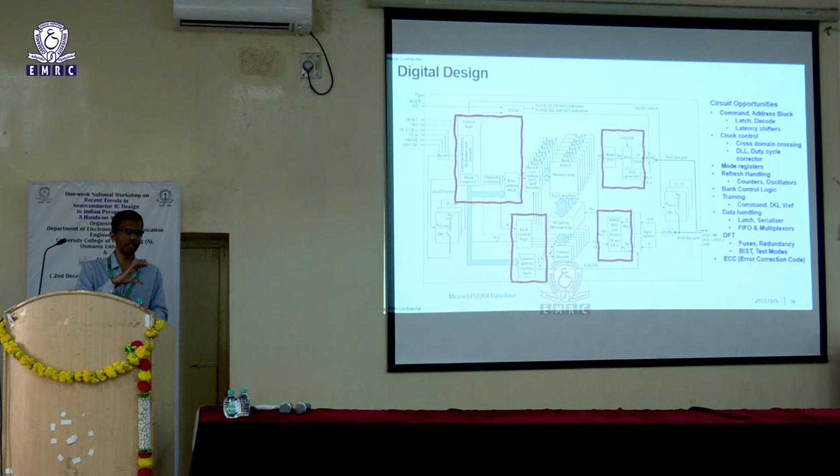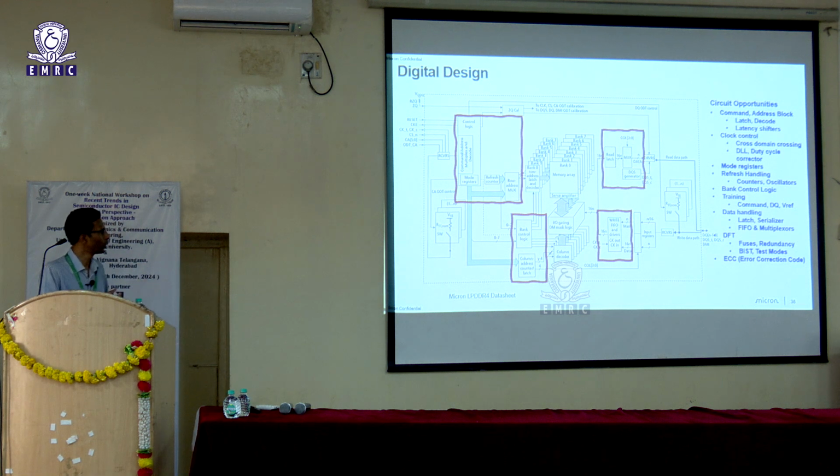So all the 200 megahertz related information is captured in one particular mode register, and you'll have a different frequency set point, say 2 gigahertz or 4 gigahertz, whatever. That is captured in a different one. So all the things that are specific to DRAM handling and DRAM operation are captured in the mode register, and that by definition is a register, and there is some amount of logic involved there as well.